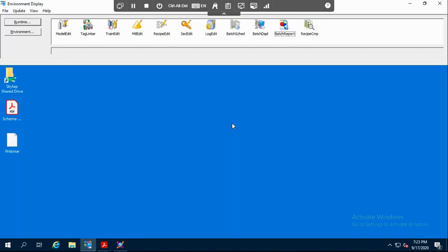You just go into your Orchestra IDE, you import your InBatch objects. You can find them under Program Files (x86), Wonderware, AVEVA Batch Management, and you will see the application objects in batch. You will have objects for the phase, for the unit, for the connections, and for the graphics. You import them, and then you will also have to connect the System Platform to the node of the AVEVA Batch Management server, which is here, for example, GR platform.